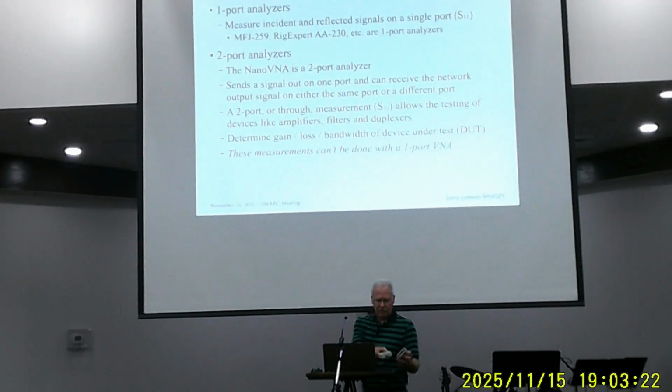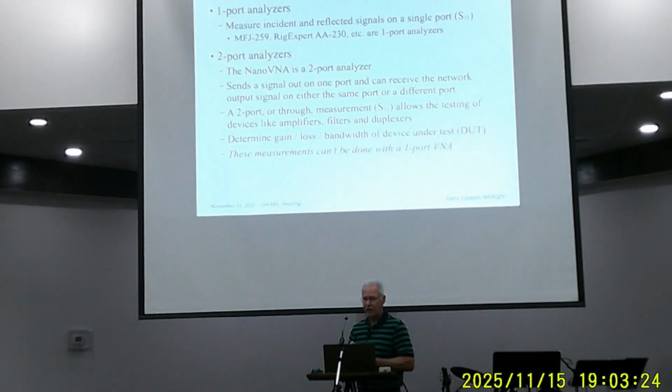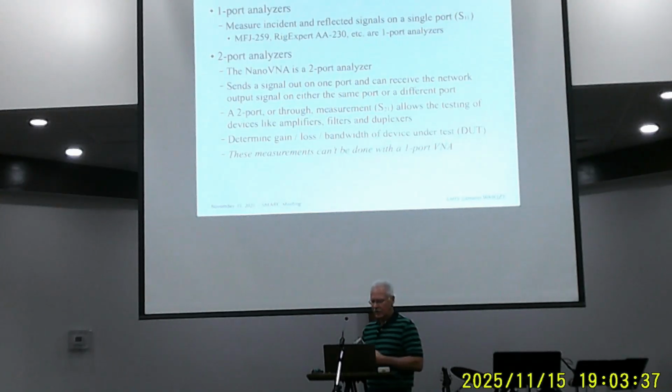The NanoVNA is a 2-port analyzer that has 2 connectors. It's similar. It sends a signal out on one port, and it can measure it coming back on the same port, just like all these others, or it can measure it on a different port.